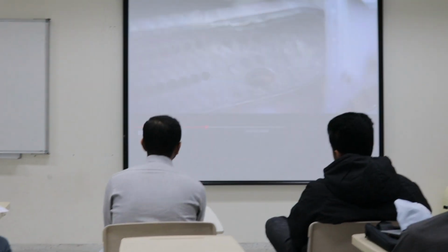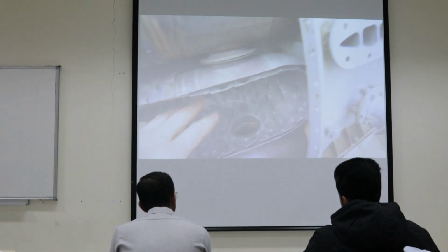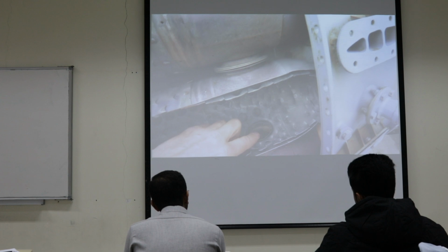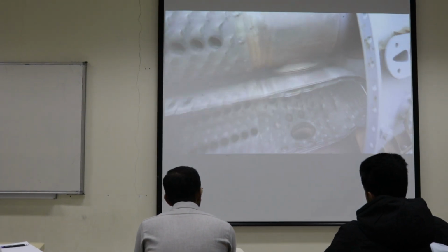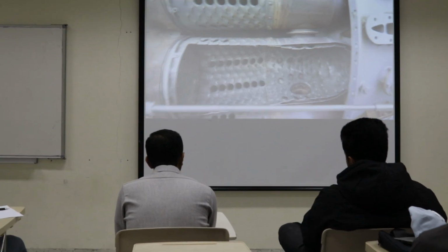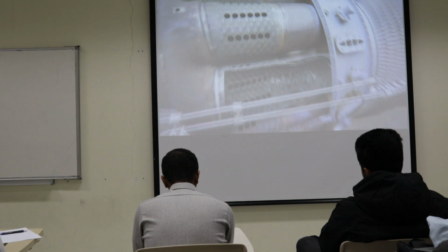They allow the flame to travel between the combustors that have ignition plugs and the other ones. Out of 10 combustors, only 2 of them have spark plugs or igniter plugs. So the interconnectors are how the fire gets all the way around.